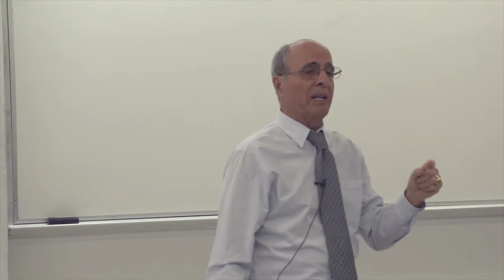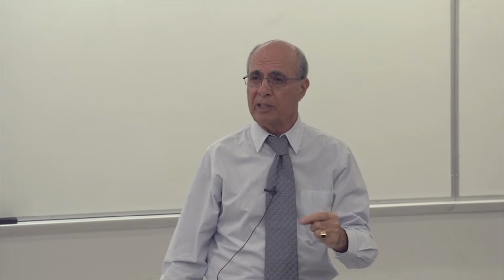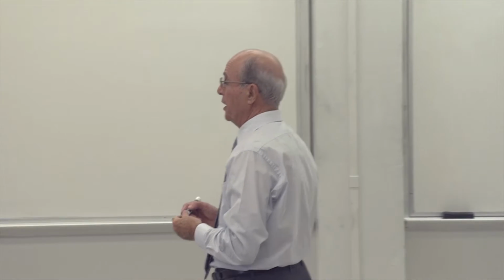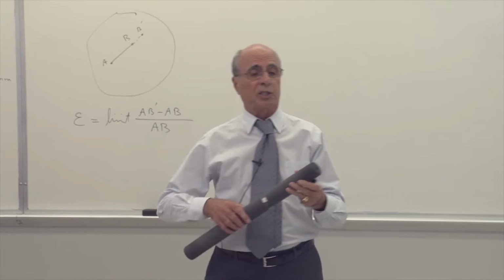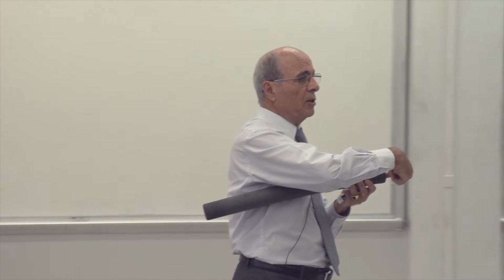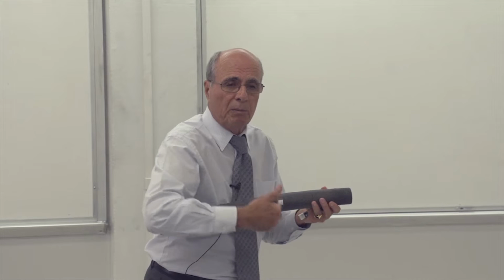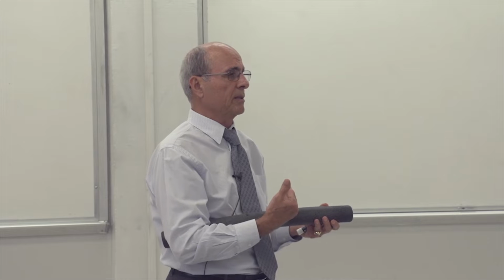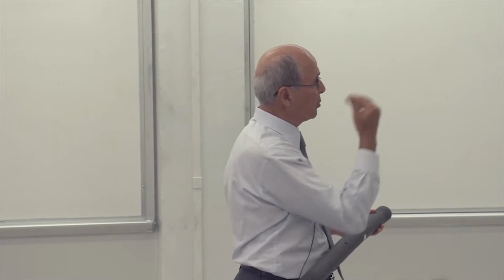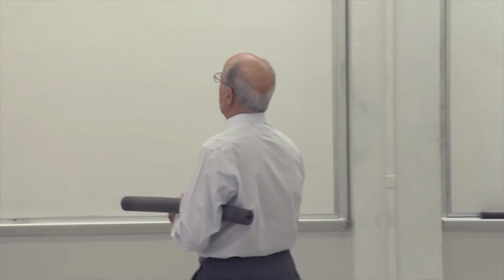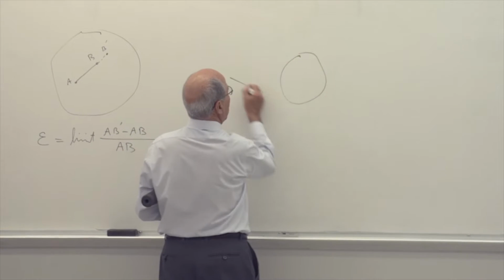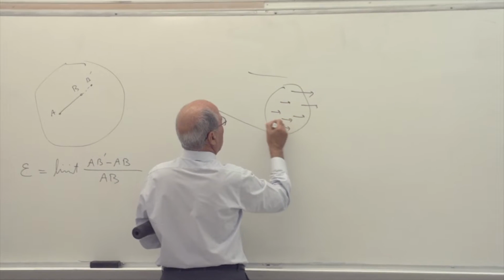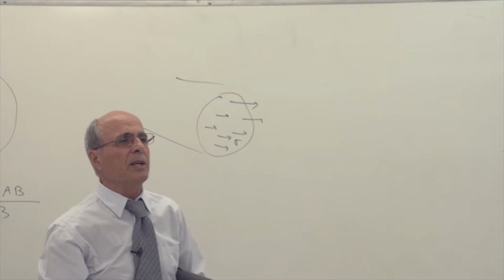Last time I gave you sigma, and everybody assumed sigma equals force over the area, which is true everywhere. But there is a change that is coming in the future. In chapter 1, the load was at the center of the rod, yes or no? The stress was uniformly distributed over the entire section. So sigma was constant. Agreed or not? In all your homework, you will see that this is what we did last time. This was the cross section, it doesn't matter how the rod moved. The sigma, if it is in tension mode, is uniformly distributed over that.